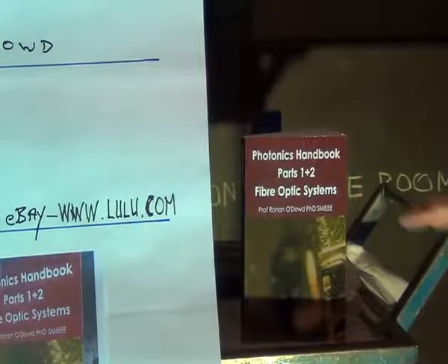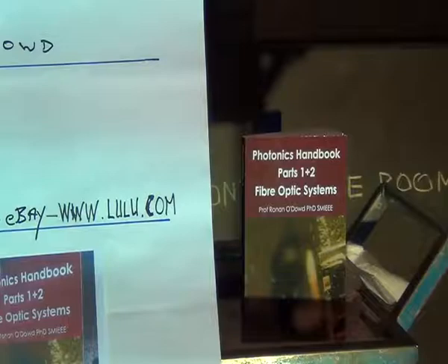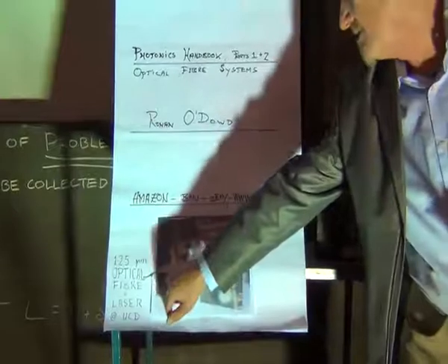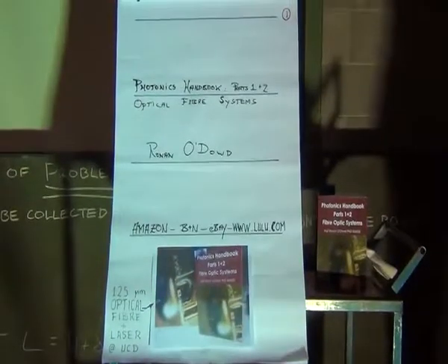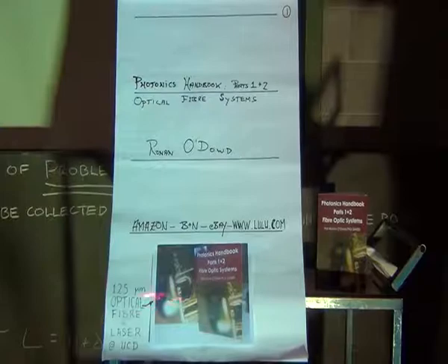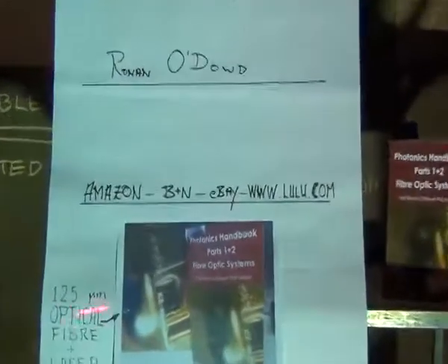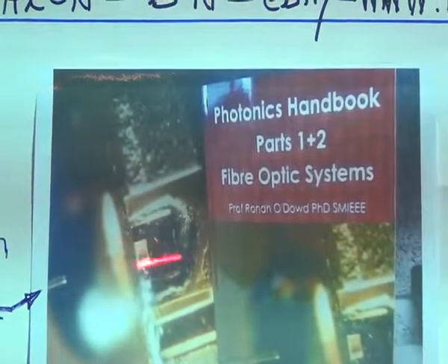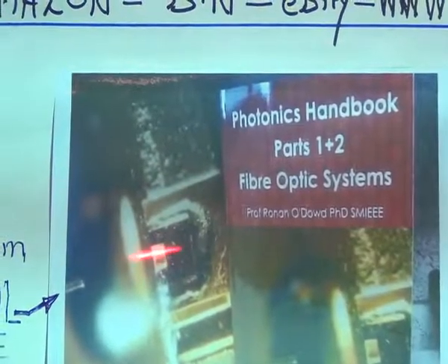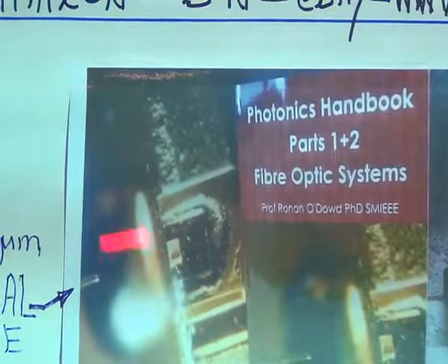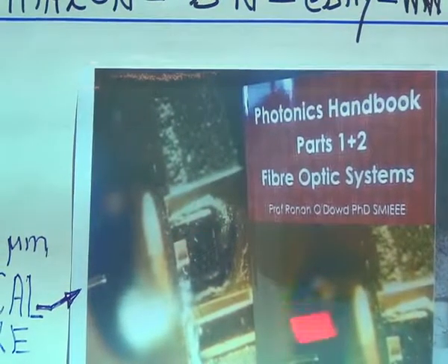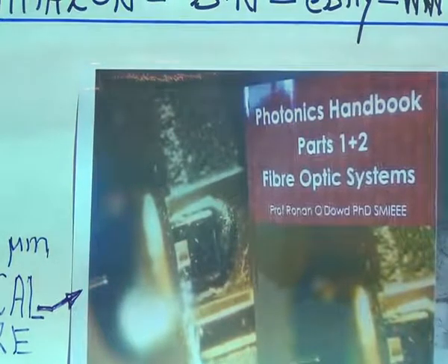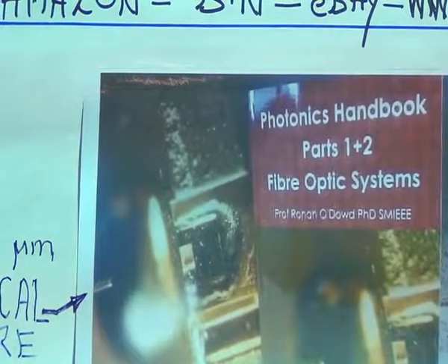Now the whole thing comes together and gives us fiber optic systems. You can see here, if you can, there's a tiny optical fiber just there. That's about 125 microns in diameter. And here, I'm pointing now at the laser. That's a semiconductor laser sitting on a gold submount, and that's on a larger mount again. The semiconductor laser is also of the same order of magnitude in size, 1/10 of a millimeter each side.